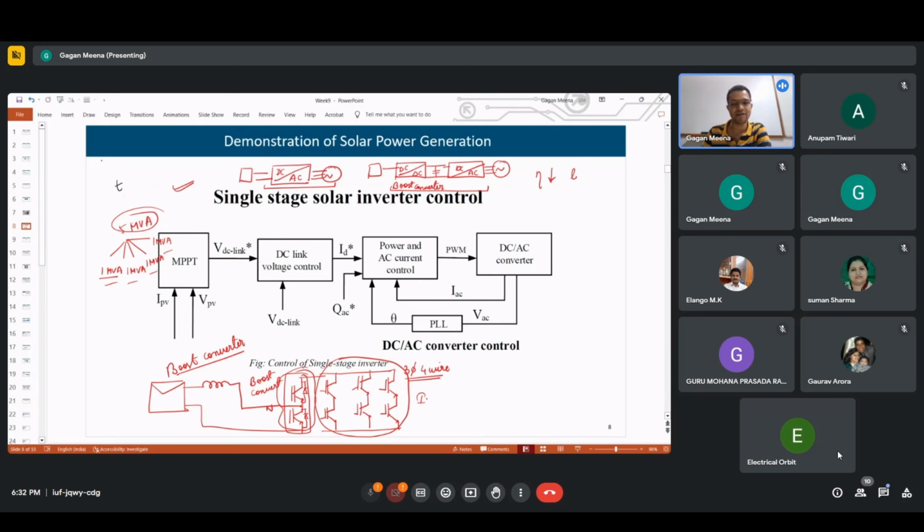So next is the battery management system. These are the main functions of the BMS. One is the monitoring of all the parameters. We want to know all the parameters. What is the state of charge? What is the state of health of the battery? So there is online estimation of state of charge and state of health, and we want to monitor voltage, current, and temperature for each cell, for thermal management and for balancing.